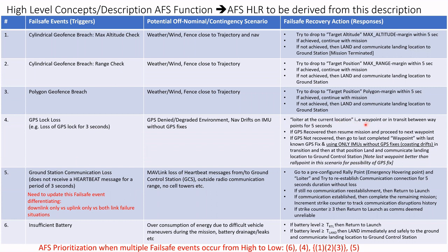That is, for instance, the ArduCopter may be between waypoints or in transit. So the idea is to loiter at the current location. And if the GPS signal recovers within that 5 seconds, then you can resume the mission and proceed to the next waypoint.